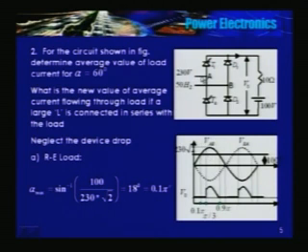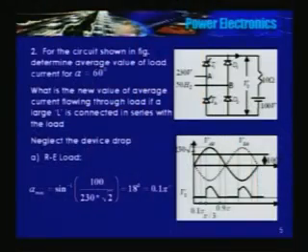So just before 60 degrees, it is E or 100 volts. Immediately after 60 degrees, it is 230 into root 2 into sine 60. So the output voltage instantaneously jumps from E to the instantaneous value of the input voltage at omega t equal to alpha. So this is why there is a jump here. Again, I am neglecting the turn on time of the device here.